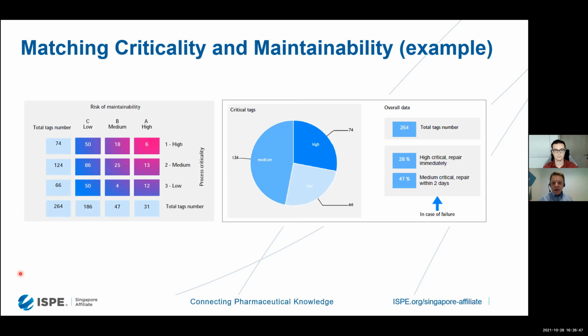The second factor is accessibility of that device for physical maintenance. The device can be installed in such a way that it's difficult to physically access it. For example, it can be in a skid, packed in such a dense way that it's difficult to access, or located at some height. In one of these situations, accessing it would require some risk, going to the site, for example.